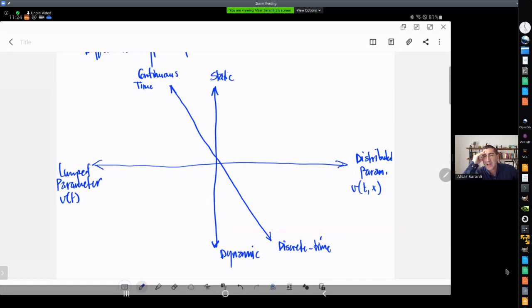In discrete time, you only care about function or variable values at distinct instants of time that are equally spaced in time. In the continuous time version, you use the Laplace transform for frequency domain analysis. In discrete time, you talk about the Z transform.